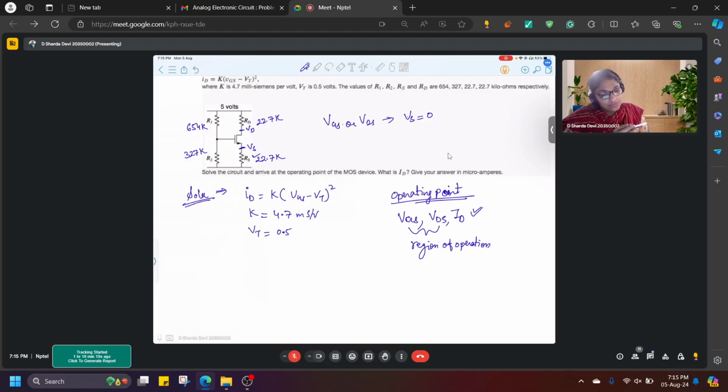So now, first here you will find Vg. Now I'm not writing Vg yet because here S is floating. So we will only be able to find Vg with respect to ground. So this will be 5 into 327 upon 654 plus 327.